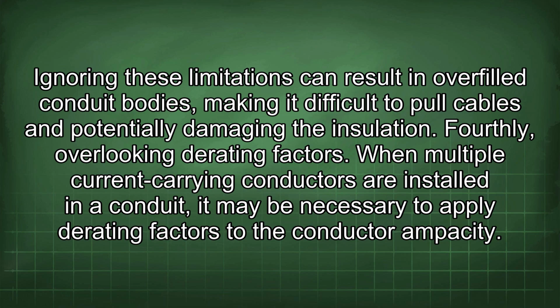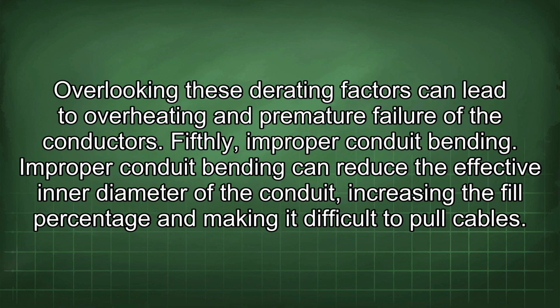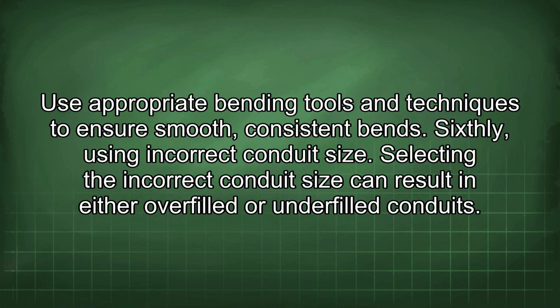Fourthly, overlooking derating factors. When multiple current-carrying conductors are installed in a conduit, it may be necessary to apply derating factors to the conductor ampacity. Overlooking these derating factors can lead to overheating and premature failure of the conductors. Fifthly, improper conduit bending. Improper conduit bending can reduce the effective inner diameter of the conduit, increasing the fill percentage and making it difficult to pull cables. Use appropriate bending tools and techniques to ensure smooth, consistent bends.